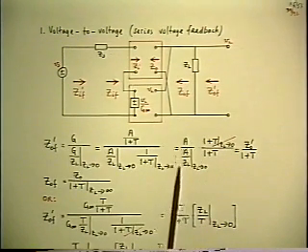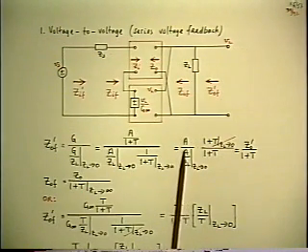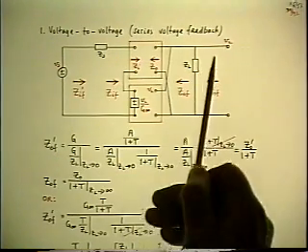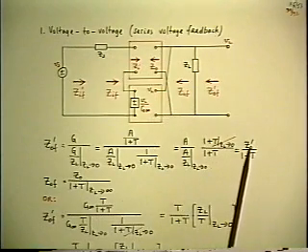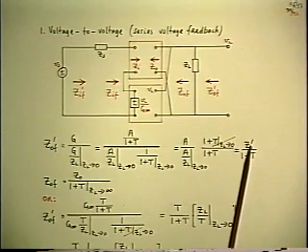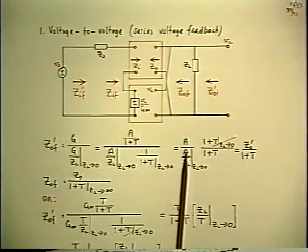Now, what is the significance of that group? It's the output impedance theorem applied to A. So it must be the original outside output impedance of the amplifier before feedback, which we've already labeled ZO prime, without the sub F. So that's the open loop outside output impedance before feedback. So that's what the A terms mean.